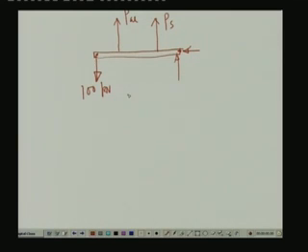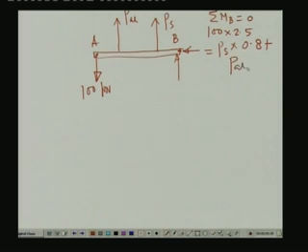And for the equations of equilibrium, if we take the moment about B, then we have moment about B equal to 0. So, we have 100 into 2.5, which is equal to Ps into 0.8 plus P aluminum into 1.8. So, the equilibrium equation is 0.8 Ps plus 1.8 P aluminum is equal to 250. This is the equation of equilibrium.